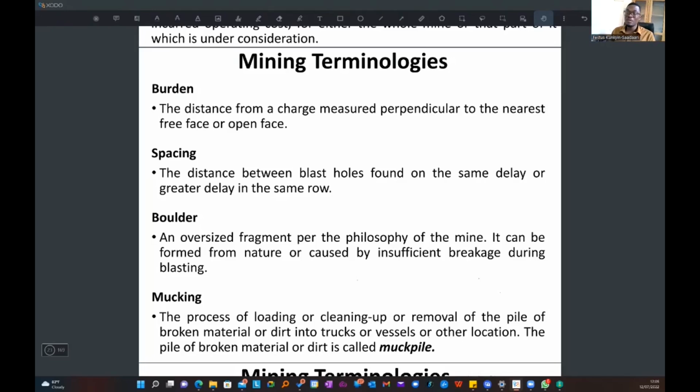In the same way, if we want to do blasting in the mining industry, the materials always swell. So assuming I drill within the space like that and I want to blast, we have to create a space for the material, because it's going to swell, so that it can swell freely. And that direction I want the material to throw itself and have that freedom is what we call the free face.